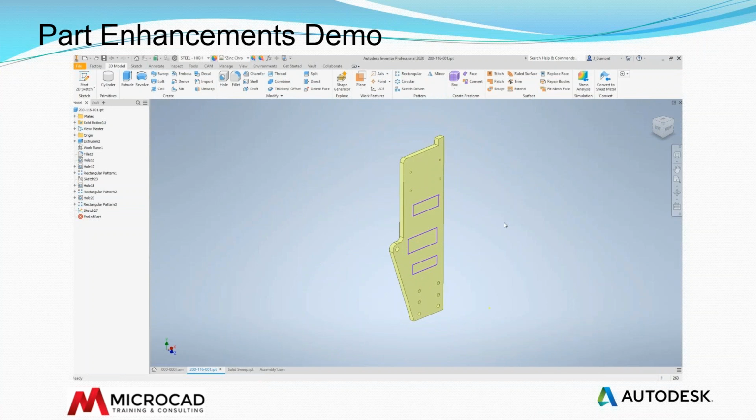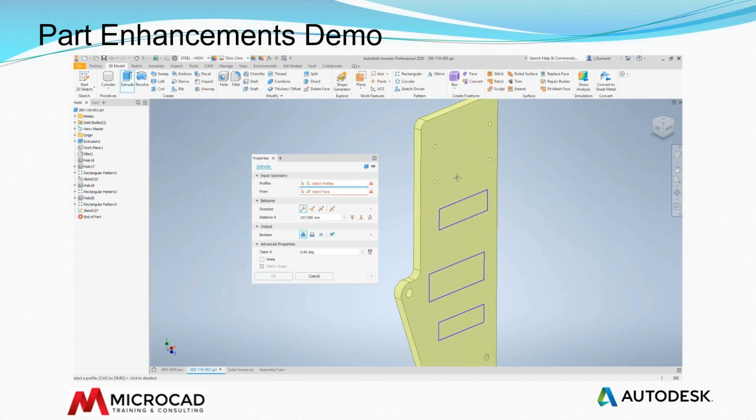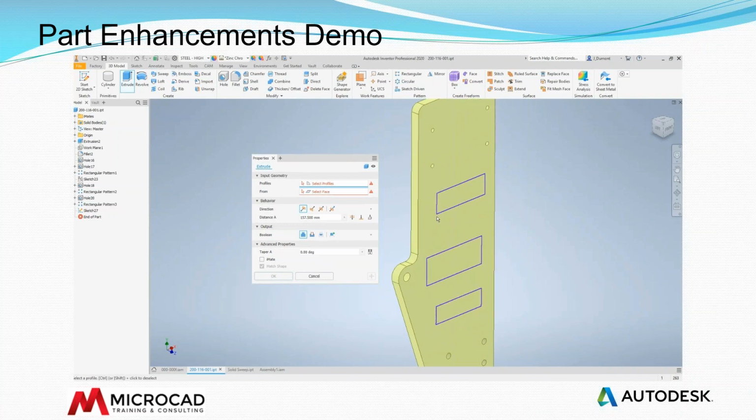So I've got one sketch, three profiles. When I use the extrude command, see the new property panel. Now, while in the property panel, you can rename the features in the sketches as you work. So the first thing I'm going to start off by doing is selecting the first profile. And when I do this, I see all the same information I would in the past with the previous extrude command. I can change the direction, change its height, and change various aspects of this.